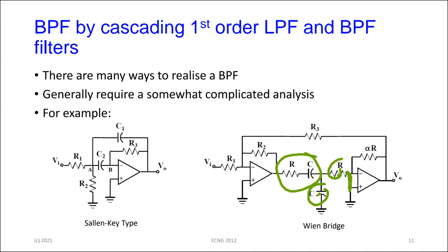The reason, of course, is that we know in the case of the Wien bridge, that the network is very frequency selective. That is how we were able to make the oscillator work, right? By selecting the values of C and R, when we did the oscillator, we could make the Wien bridge oscillator oscillate or resonate at a very precise frequency.